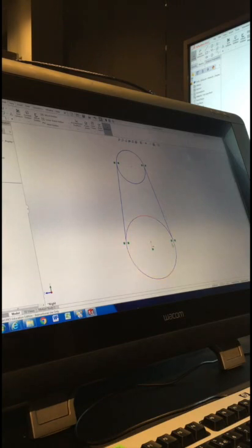So what you should see is your main circle at the bottom has a coincident relation with the center point, and then in each of those sort of four corners, you have a coincident and tangent relation. All right. Now, what we're going to do next is try and get this sketch fully defined. All right. So you'll be able to see what that means for the first time.